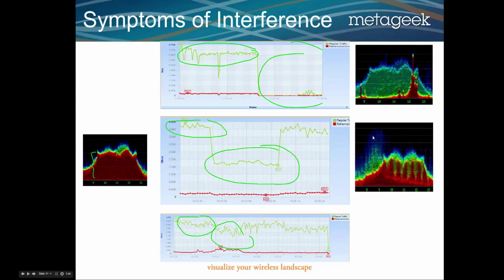Now the next example might surprise some of you. That's because we see something like this. It kind of creates a mountain shape and it spills over. If you look here, it spills over into the Wi-Fi network on channel 11. Okay, and it's not constant. It's definitely green, so it means that it's probably 40% utilization. So it's not transmitting all of the time, but it is transmitting, and it's releasing RF activity. Now this is a microwave oven.